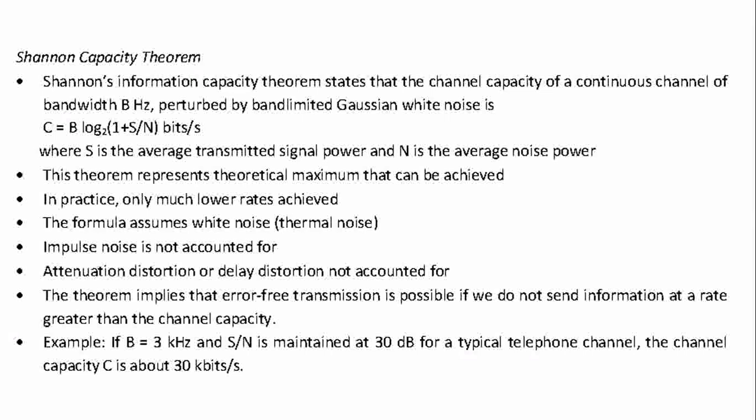If the transmission channel is very narrow, of course you expect that you're going to have a lot of noise. So you must increase the transmission channel for you to avoid the noise. With this one, there's a formula that we use, C equals B log 2 of 1 plus signal to noise ratio, where C basically stands for the transmission channel capacity and B is the bandwidth.